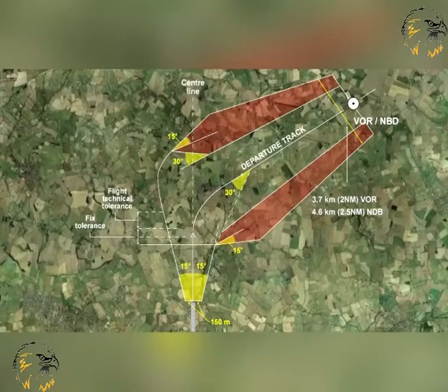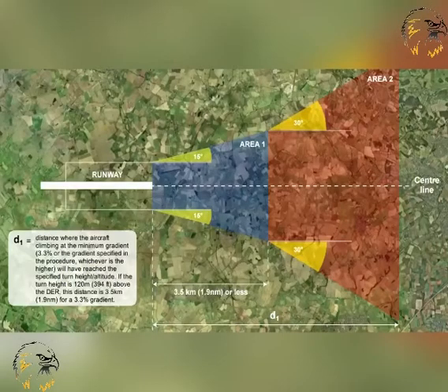In the event of in-flight emergencies post V1, aircraft operators are required to provide contingencies that deal with safe operation of the aircraft during this phase of flight. An omnidirectional departure procedure is designed when no track guidance for departure is available. Departure criteria are developed using undefined omnidirectional initial departure tracks.